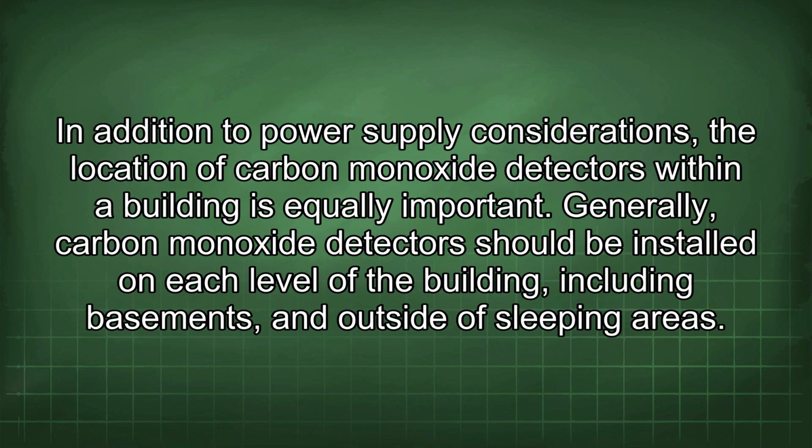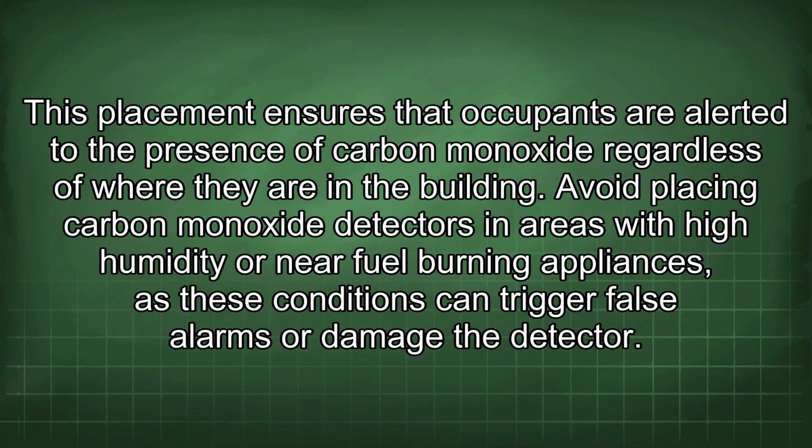In addition to power supply considerations, the location of carbon monoxide detectors within a building is equally important. Generally, carbon monoxide detectors should be installed on each level of the building, including basements, and outside of sleeping areas. This placement ensures that occupants are alerted to the presence of carbon monoxide regardless of where they are in the building.